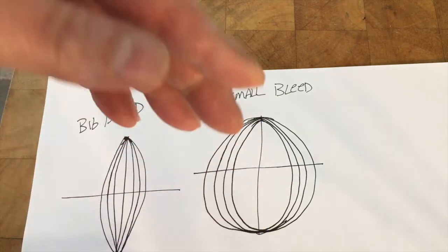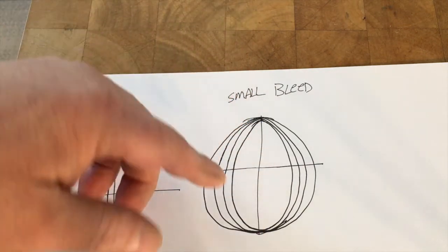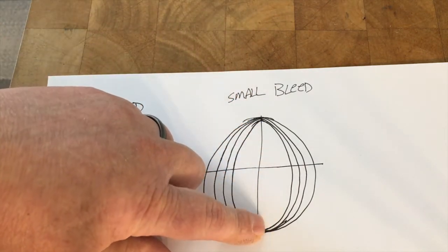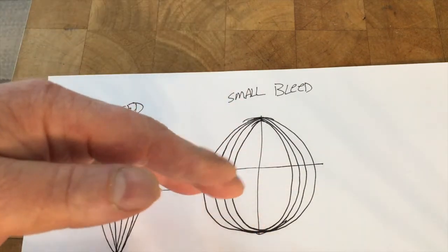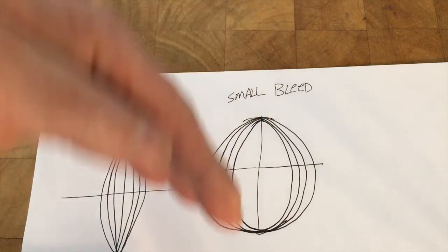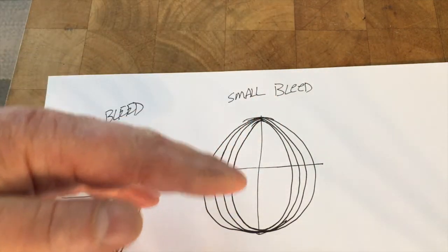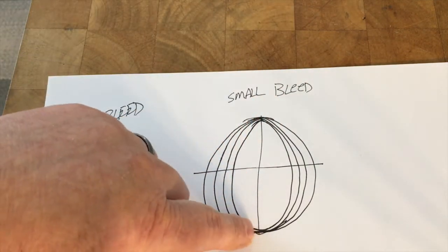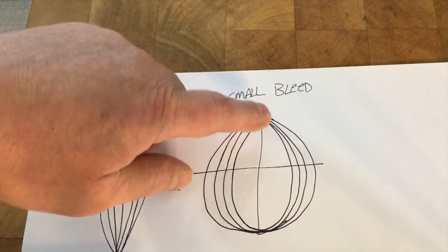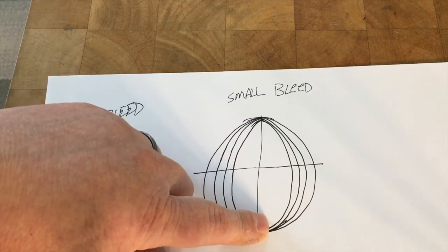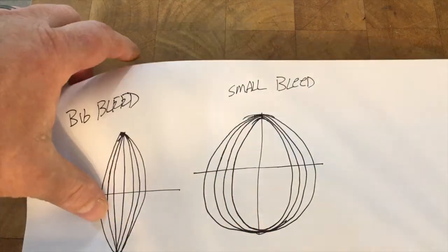That's because a lot of the time your traction in shocks happens to be where the shock changes direction because you're going over bumps. So when the shock changes direction, it's real important to figure out what you want for bleed, and bleed is a huge tuning tool for shock people and people that get into it.